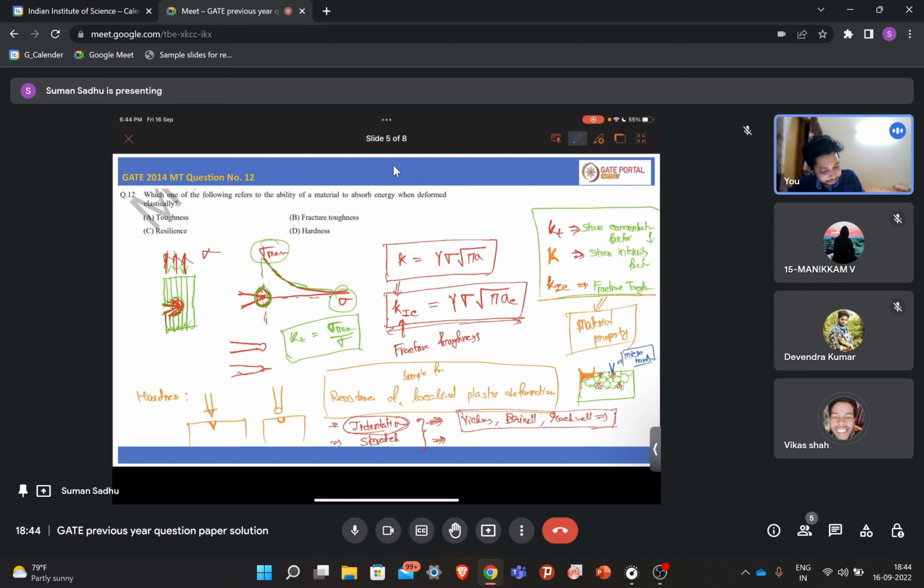So in this case, this hardness will be only of this phase, not for the other phase or for the whole material. So you have to express it according to which technique you are following to measure the hardness of your sample. If you are measuring for the bulk sample, and you are creating a large amount of indentation, or a larger indentation size, then you can say it is the average hardness of your sample.